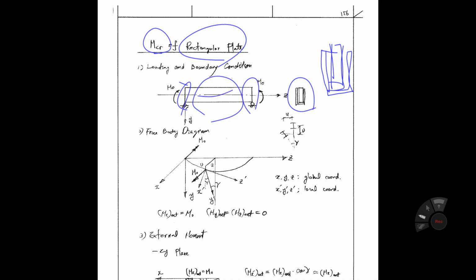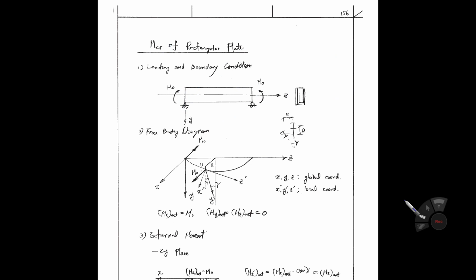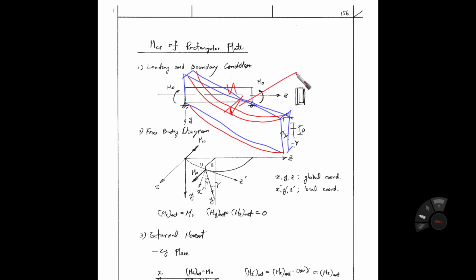Firstly, you have to understand the coordinate system. As I mentioned before, for this kind of column, the coordinate system is simple because it is a 2D problem, okay? X, Y. There is no rotation. It is simple. But as I mentioned, this torsional problem is a 3D problem. If I draw again, that is the beam. Let's consider the deformation due to lateral torsional buckling like that. It means it has a vertical deformation as well as lateral deformation. Laterally you have the deformation like that, and vertically deformed like that. This lateral displacement is called U. This vertical displacement is V.